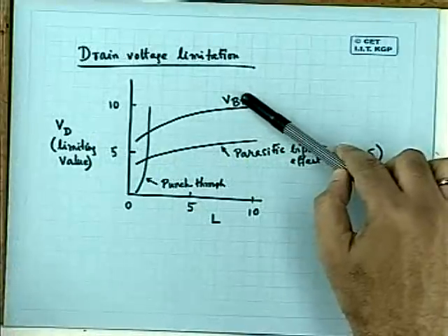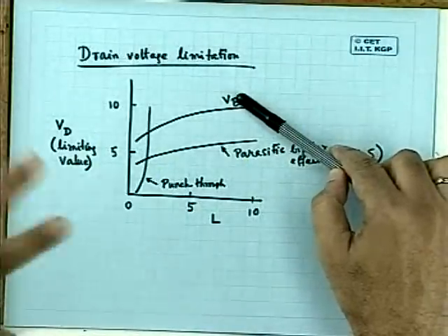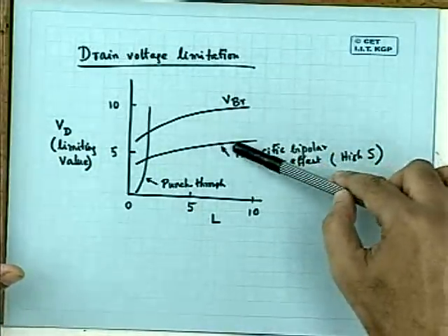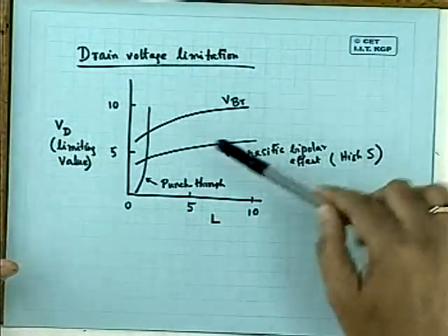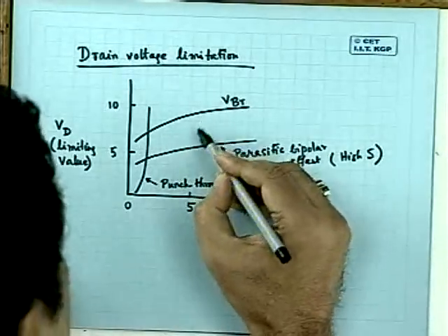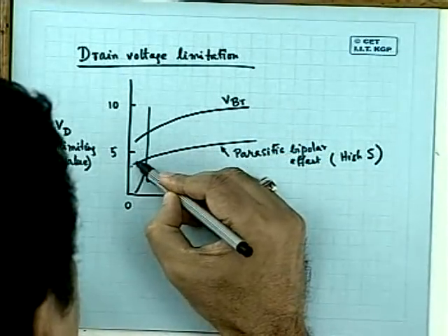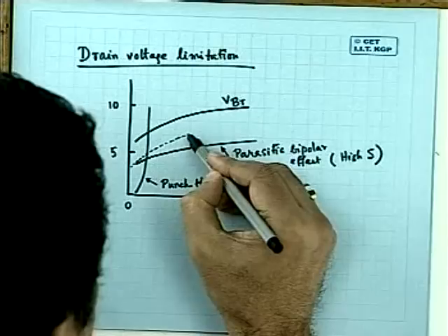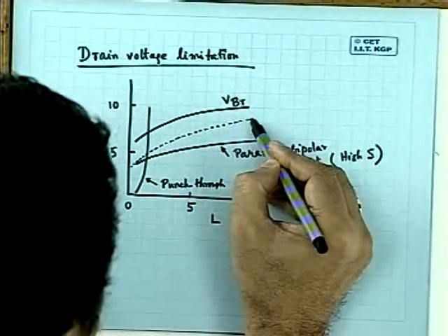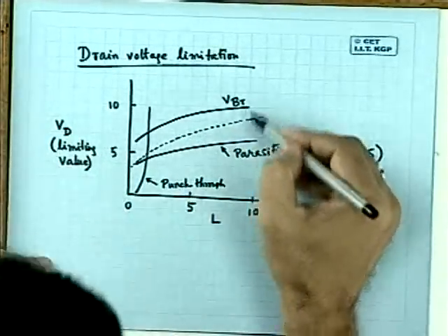But then as you increase the doping, punch-through dominates. So you are in a trap. Initially you are under the trap of breakdown voltage, avalanche carrier multiplication, etc. Then the parasitic bipolar effect is not that serious. In fact, therefore we draw a curve, something intermediate like this. You should be below this line.